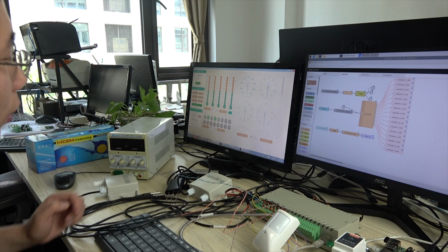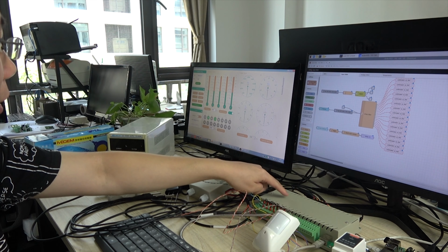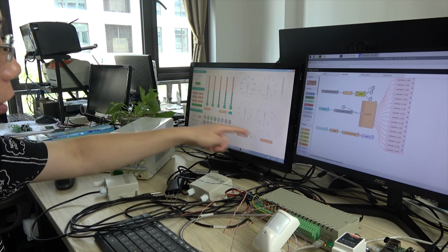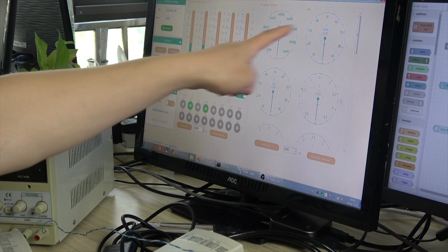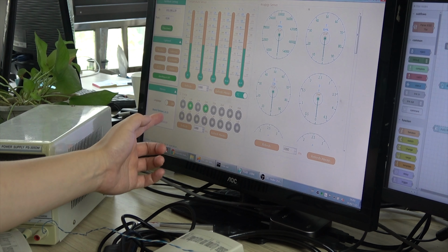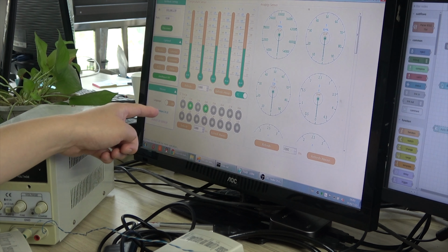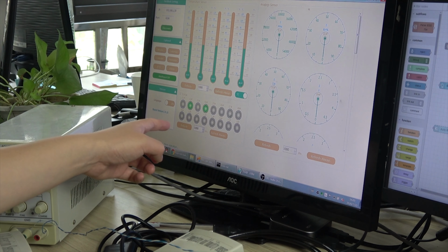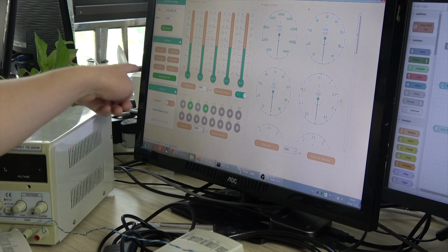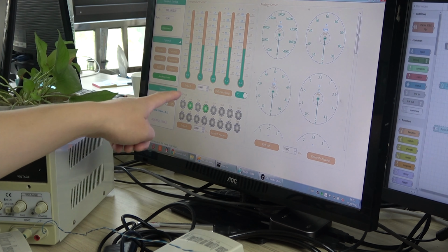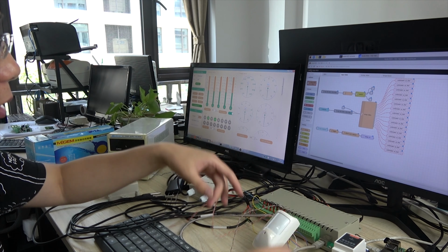Now let's begin. First, we can see this window. This program is our PC software for this COL box. It can monitor all these sensor states, such as the temperature, digital input and analog input. This PC software can not only show the values, but also set the automatic commands. So when to control the relay and what condition triggers the actions, you just use this software to set. But in Node-RED, we will create the UI interface to display all the sensor values.